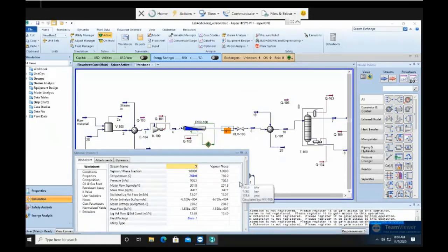So when that happens, the operating condition has to be set outside the PFR, okay, not at the front. Remember this. The operating conditions of all the equipment are to be set outside, because we are taking the assumption that everything is perfectly mixed in the system. Even though that is a bad assumption for plug flow, it does not really matter, because we cannot actually set the temperature and pressure inside the plug flow reactor. So this is only an estimation.